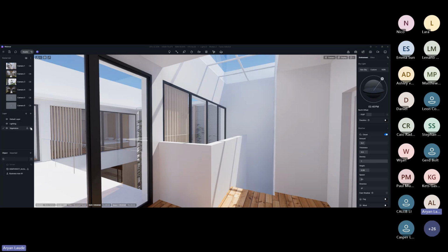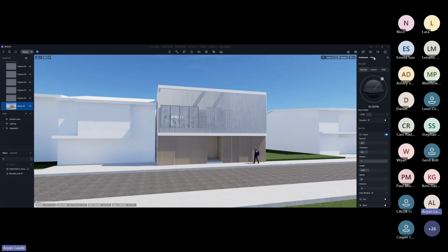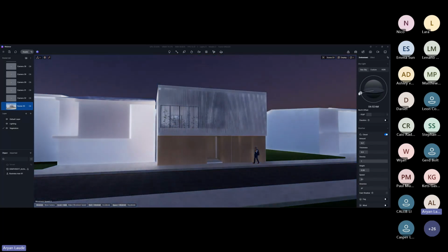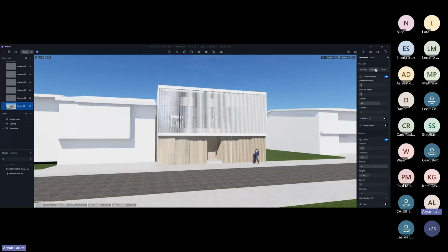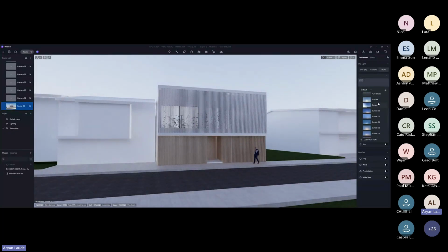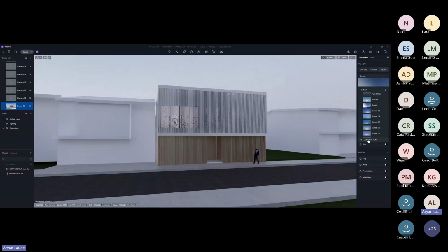And finally, the last part of the user interface, which is on the right side, we have our environments and effects, wherein all of these settings contribute to what our final output is going to look like. If we make some adjustments to these sliders, it will instantly be reflected in D5 Render. So we can change the environment using geo and sky, custom daylight, and custom nighttime. We can also utilize HDRI backgrounds. With D5, we have a lot of HDRI backgrounds that you can easily and freely use. But if you have your very own, you can freely import your own as well.